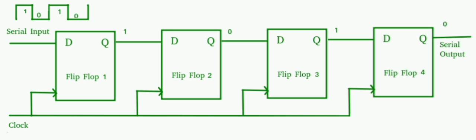parallel out; PISO, parallel in, serial out; and PIPO, parallel in, parallel out. In SISO, the 4-bit right shift SISO register: in a right shift SISO register, the data is applied at the MSB flip-flop, that is, the D flip-flop. For an n-bit register, to enter n-bit data requires n clock pulses in serial form.